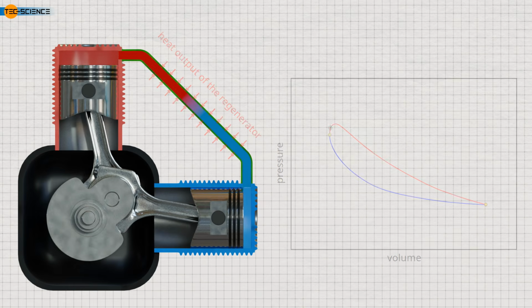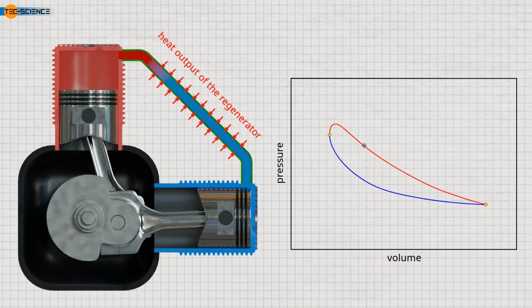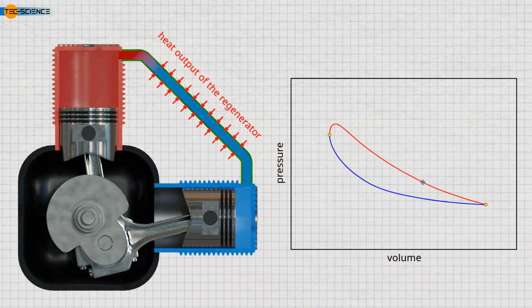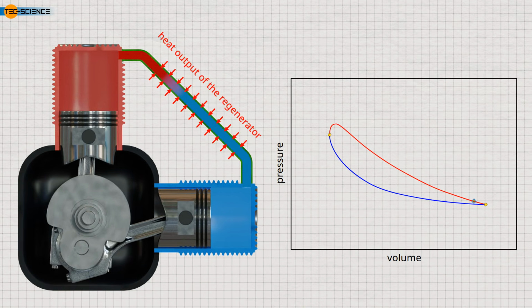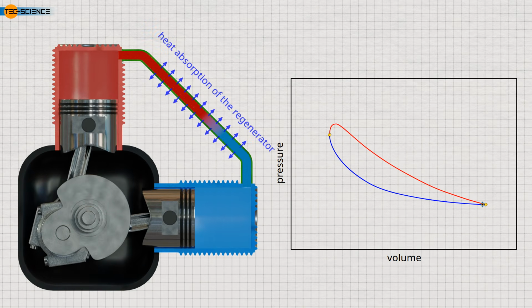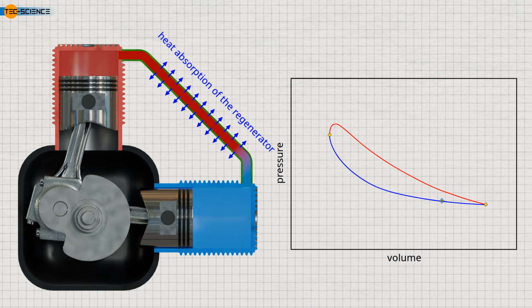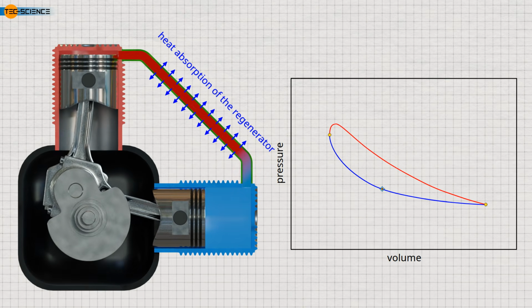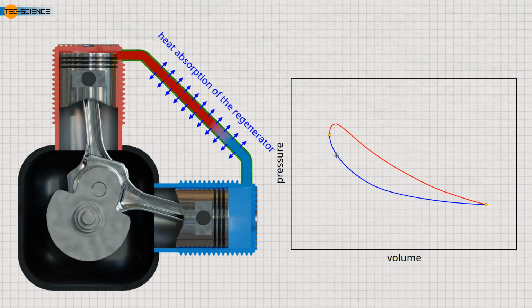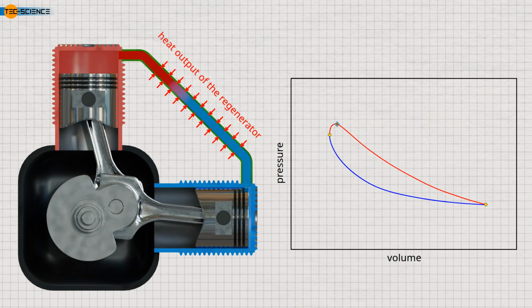of the Stirling engine. In this way, heat is removed from the gas while it flows from the hot cylinder to the cool one, resulting in enhanced cooling. As a result, compression can occur at a significantly lower pressure compared to a process without a regenerator. Consequently, the work required for compression is reduced.